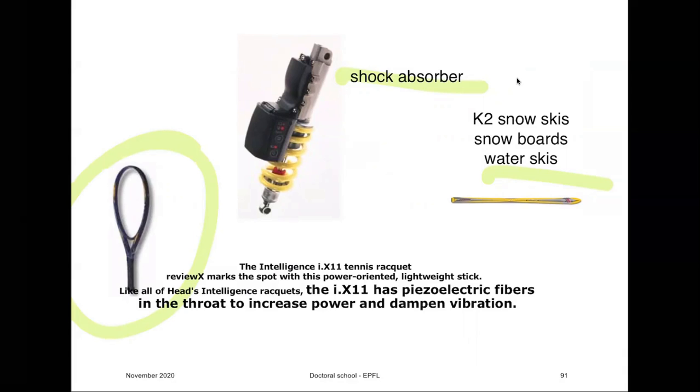So if you have piezoelectric fibers inside, you can transform a part of that elastic energy into electrical energy and dissipate it through some resistors and remove the vibrations.